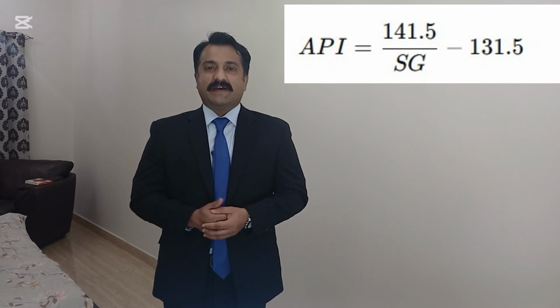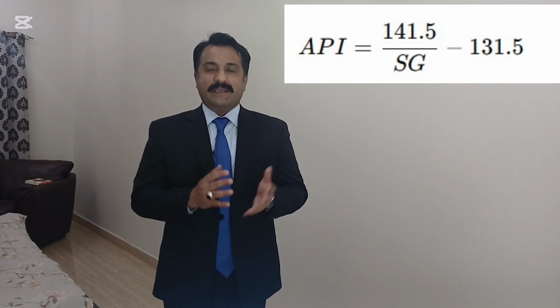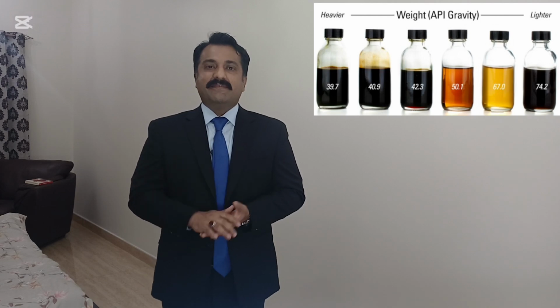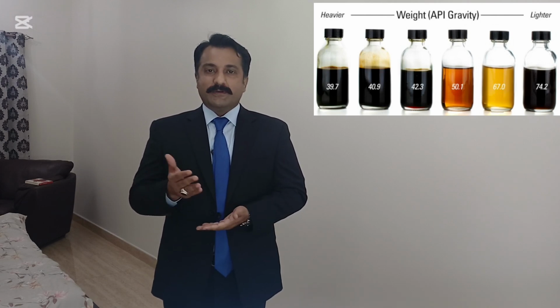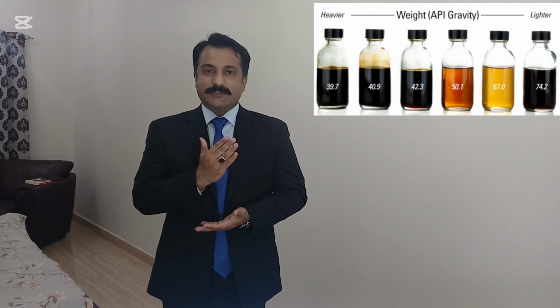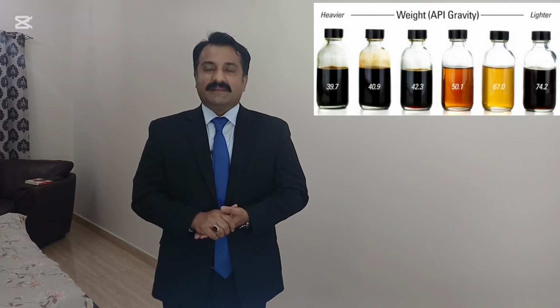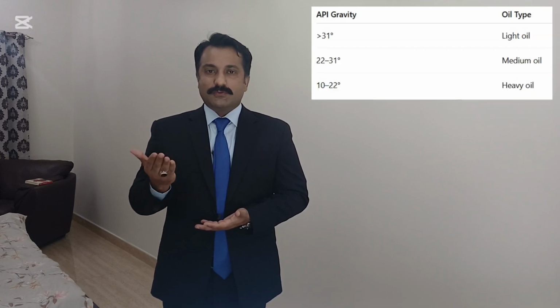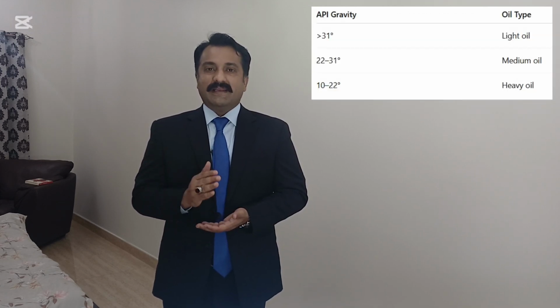Oil is classified on the basis of API gravity. If API gravity is greater than 31 degree, the crude is lighter. If API gravity is in between 22 to 31, then the crude oil is medium. If the crude oil is between 10 to 22, then the crude oil is heavy.